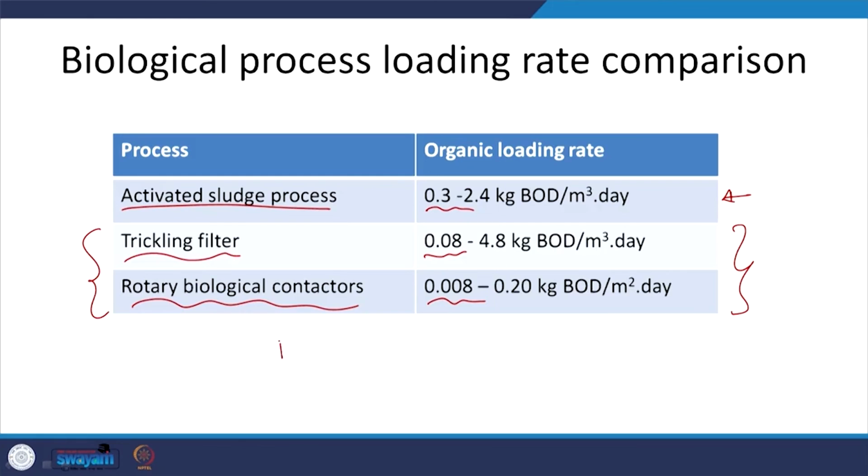As I mentioned, that is why I had the reminder with respect to MBBR. So, you can have both suspended and attached. Some people have looked at providing media, and the media can be these kinds of MBBR, moving bed biofilm reactors. So, this will be pumped in, this is air coming in, and this is my media upon which the microbes will grow. So, that is the MBBR system.